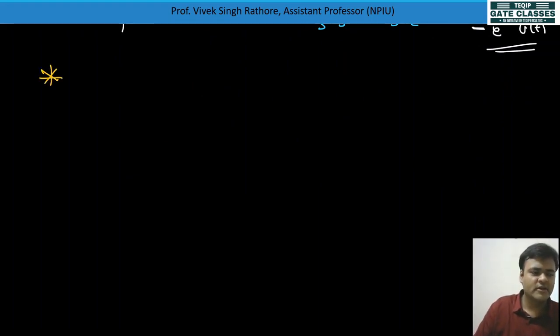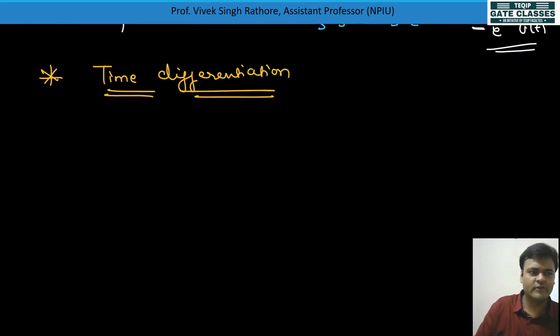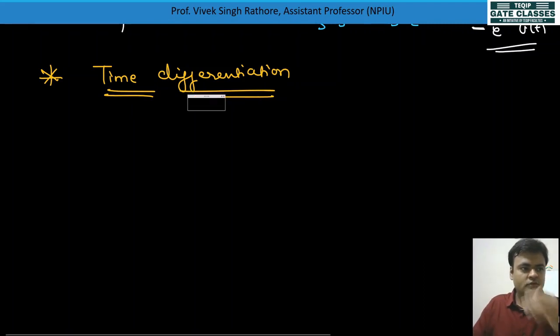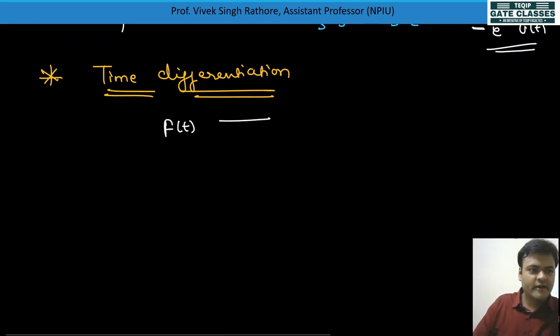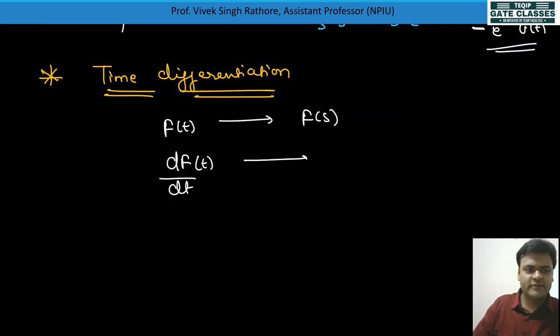The next property is the time differentiation property. We'll try to finish this Laplace transform in today's lecture only, and we'll not move on to the next lecture. So what is the time differentiation property? It means that if f of t has Laplace transform F of s, then if we do df by dt, that is differentiation in the time domain, what happens in the frequency domain? It will just multiply s into F of s.